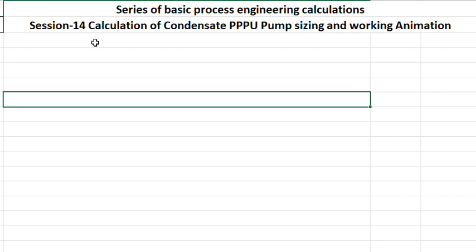When it comes to pumping the collected condensate, the centrifugal pump proves to be highly limiting and costly, as the condensate is at high temperature, approximately 80 to 90-95 degrees Celsius. So there are some limitations, and several manufacturers, like Forbes Marshall or Spirax Sarco, provide specific condensate pumps.